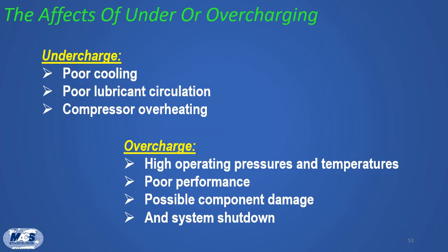Undercharges can result in poor cooling and, even worse, poor lubricant circulation, which can lead to compressor failures. Overcharges can result in high operating pressures, which can also cause poor cooling performance and even component damage. During hot weather conditions, overcharged systems can experience system shutdown from the high side pressure control switch or sensor due to high system pressure.